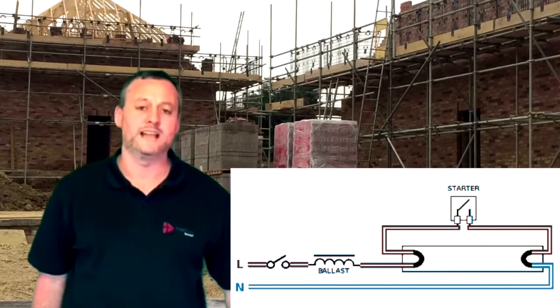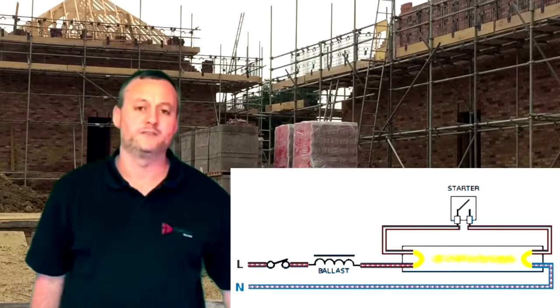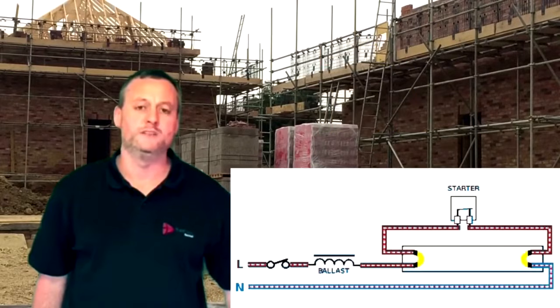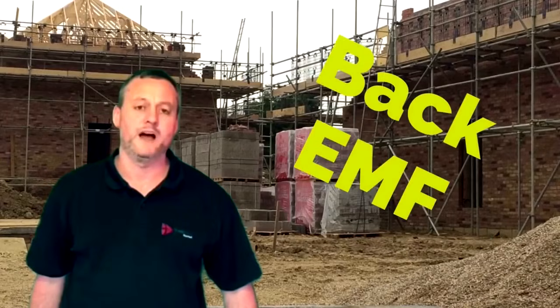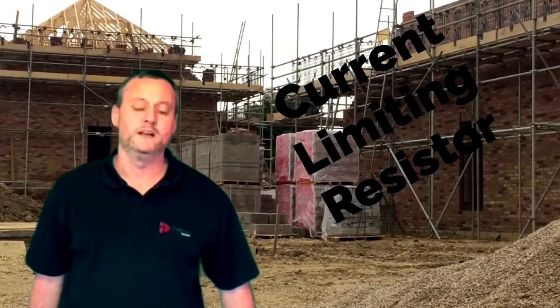What happens then is the gas starts to cool. It opens the blades within the starter, causing the massive back EMF developed by the choke to be dropped across the very low resistive tube, causing the tube to ignite or light. The questions in the exam are more based on what the ballast is doing in circuit. So on starting up, the ballast is there to develop the large back EMF that drops across the low resistance tube. When the lamp is illuminated, the job of the ballast then is to be a current limiting resistor in circuit.